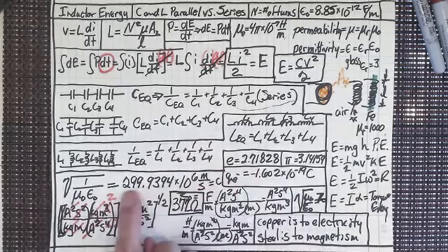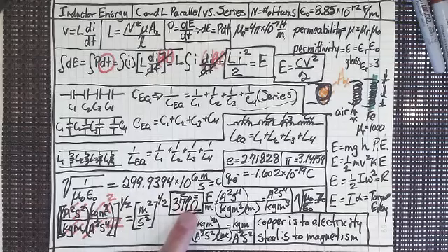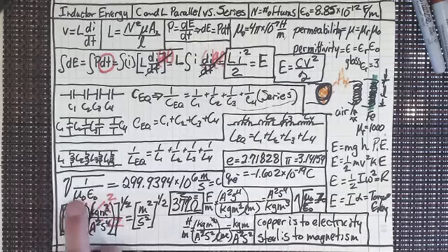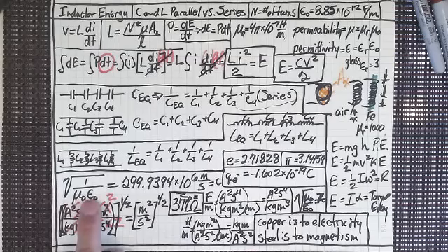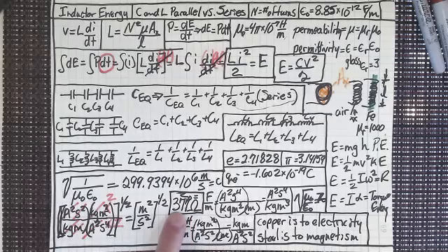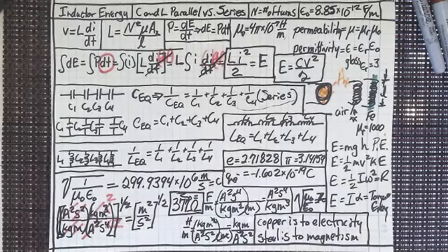So not only does this tell us what the speed of light is, it also tells us what the impedance of outer space is, right? And of course, the impedance of outer space is the impedance of the atmosphere too, because both of these are very close to the same constant in the atmosphere. For air, mu sub r is very close to 1, and epsilon sub r is very, very close to 1. So when we're broadcasting microwaves through the atmosphere, we're looking at an impedance of 377 ohms. That becomes more important later on, when you'll be taking electromagnetic waves and stuff.